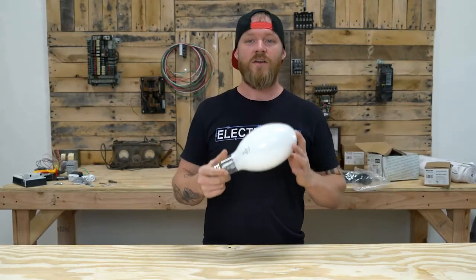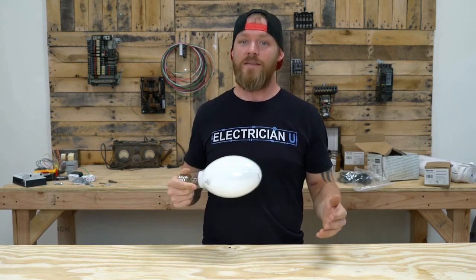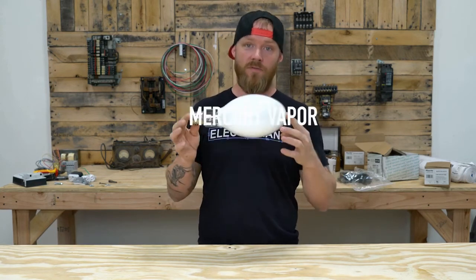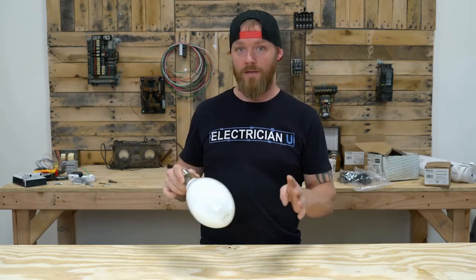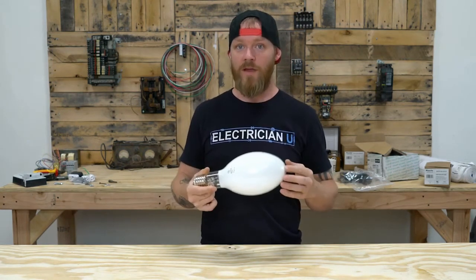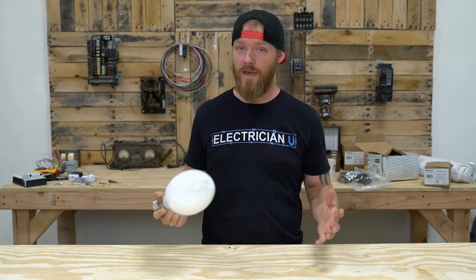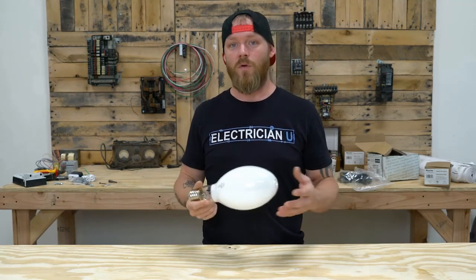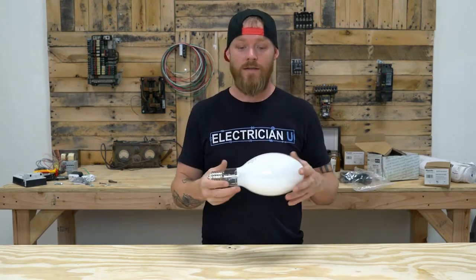So the next type of lamp I'm going to talk about is another bulb that's in the HID family. This is the mercury vapor lamp. All three of metal halide, high pressure sodium, and mercury vapor utilize mercury inside of them. That's really the only thing that they have in common, except for the fact that they're igniting an arc through a gas.